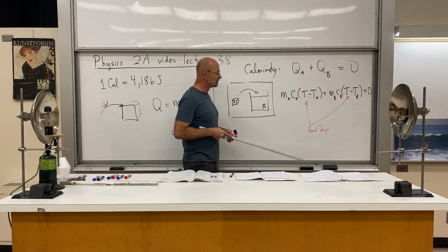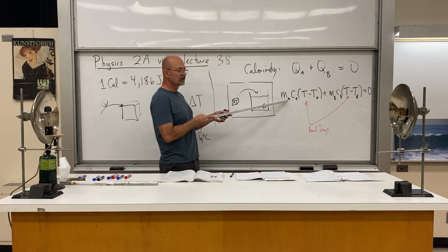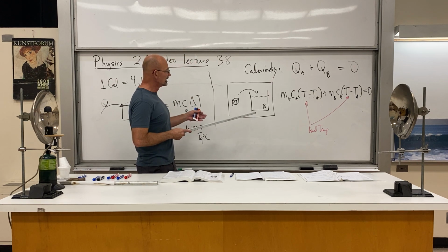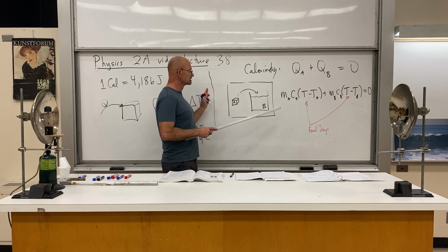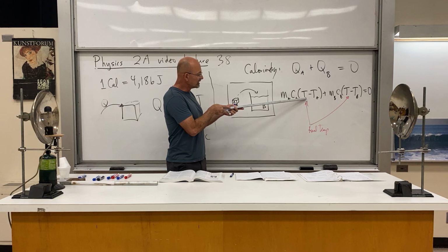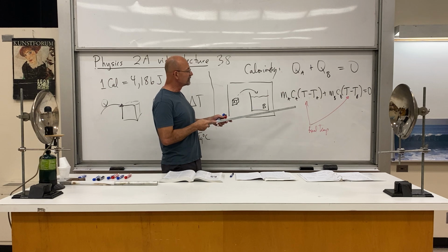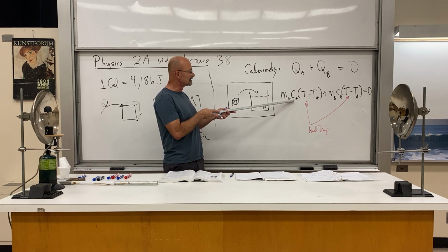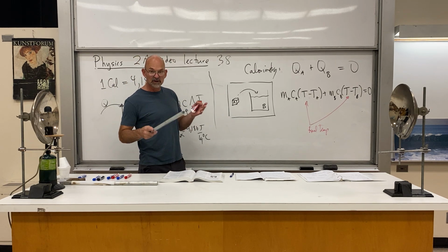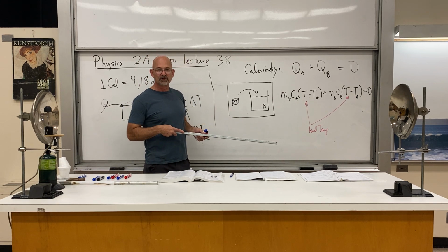For example, we know the specific heat of water. Suppose we wanted to know the specific heat of copper, because we don't know it yet. Then we measure things carefully, measure their initial temperatures, pour the copper into the water, close it all off, and wait a while, and then we finally get this temperature here, T final. Write that down as well, and then we'd be able to calculate the unknown specific heat of copper. And different substances have different specific heats. You probably saw that if you looked it up in the tables. And that says something about their internal structure, actually.